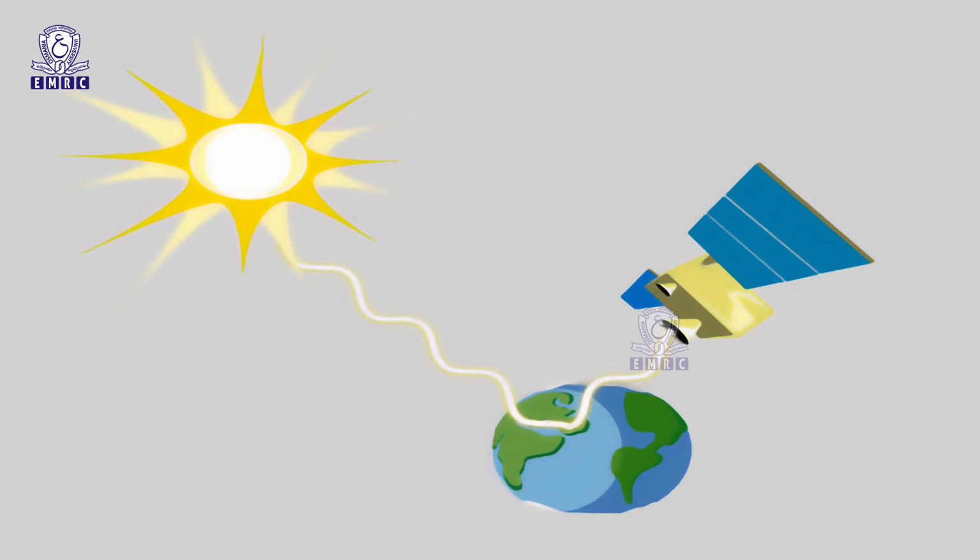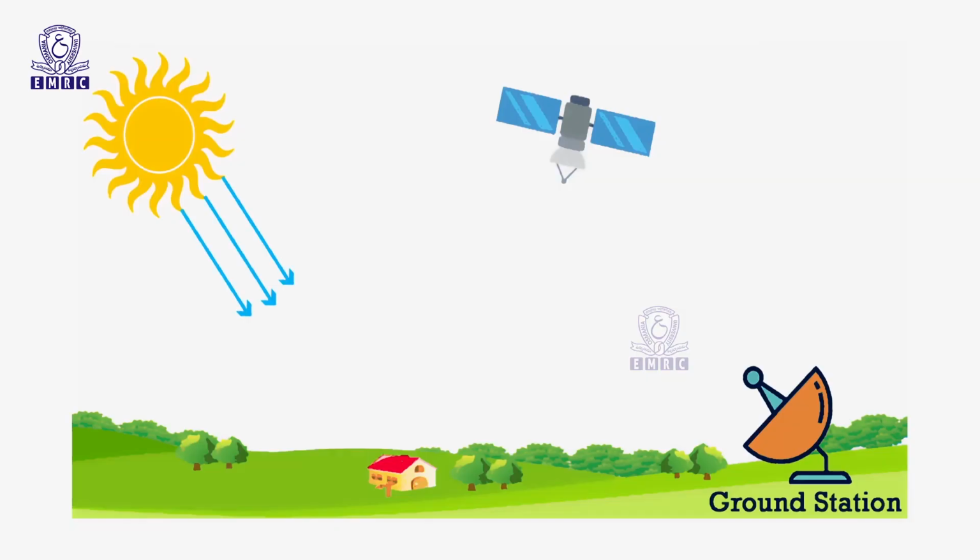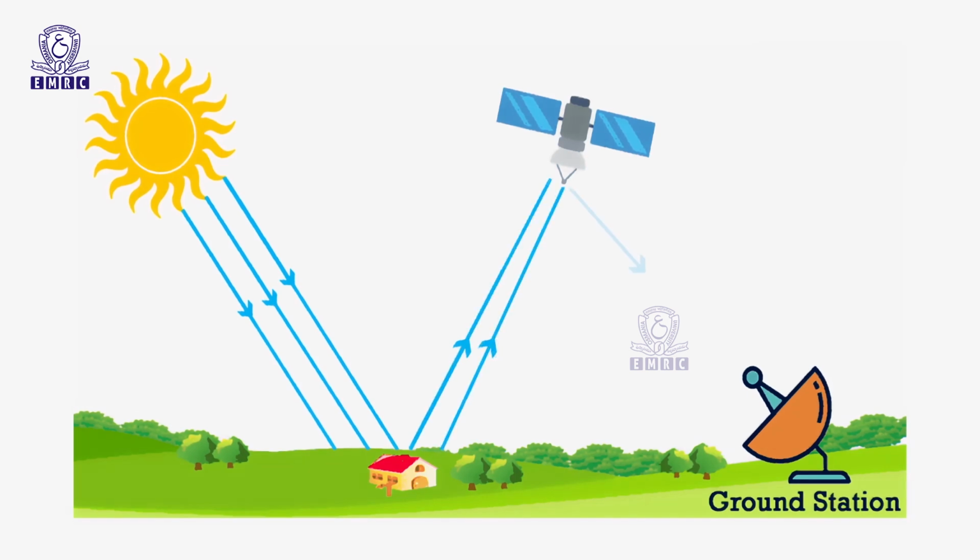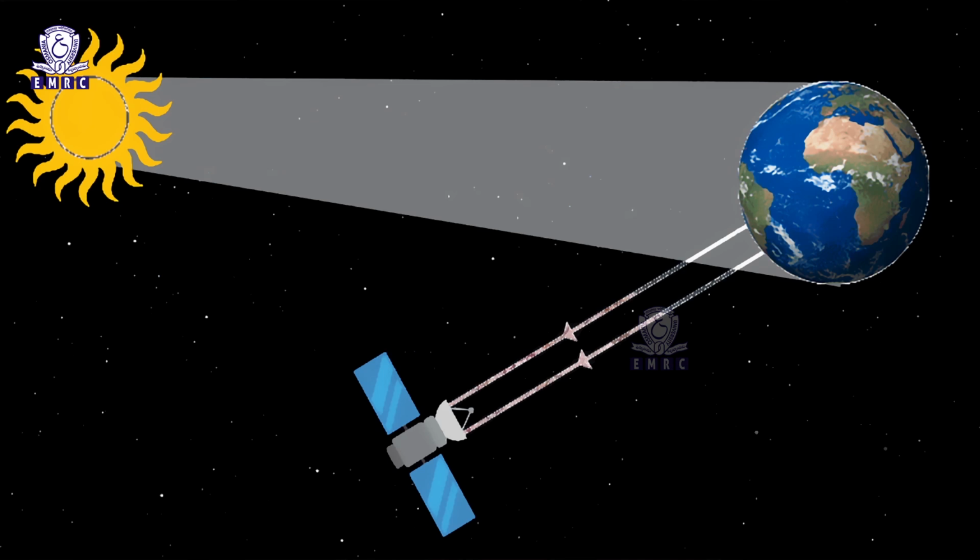Passive remote sensing offers less noise control as the source of the energy is primarily the sun and it is out of control of the surveyor. Passive remote sensing delivers less accurate measurement readings of the ground objects due to the variation in sunlight affected by the weather conditions. Passive remote sensing uses radiation signals from old satellites that are easy to operate and also focuses on land use, land cover analysis and small scale mapping requirements. Passive remote sensing has small datasets collected and does not allow for detailed interpretation of information acquired.